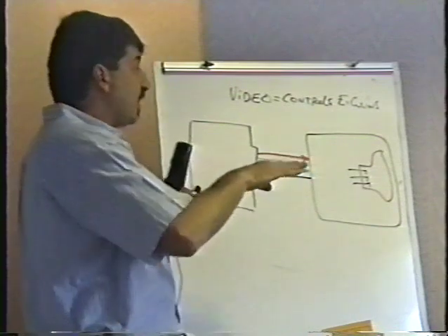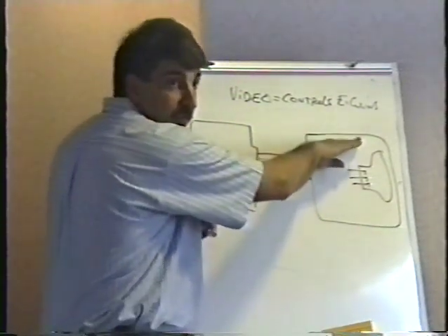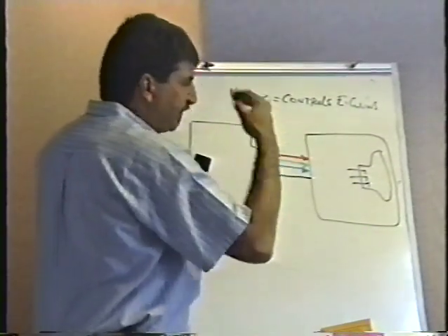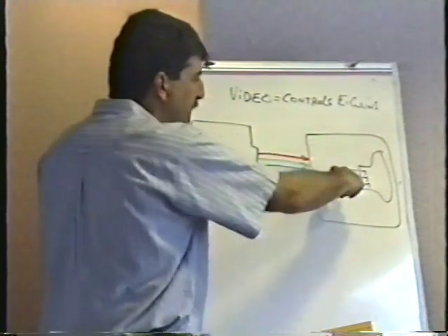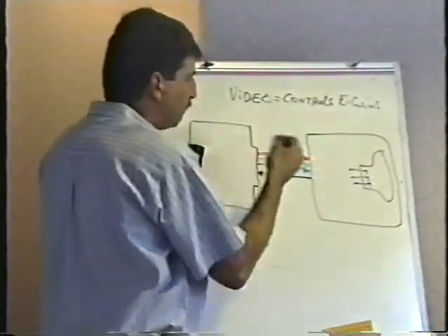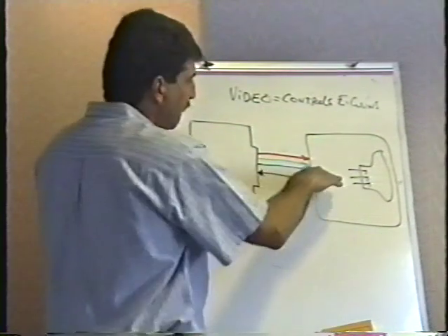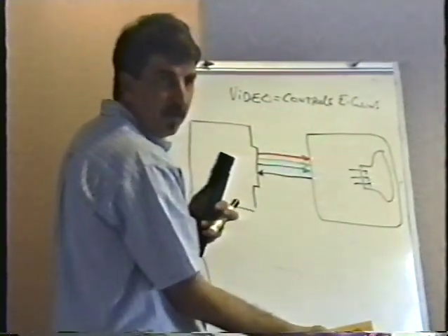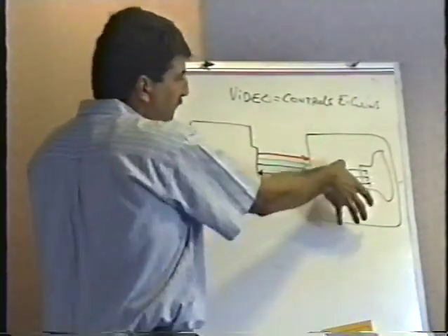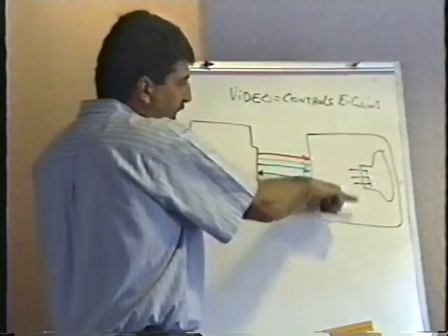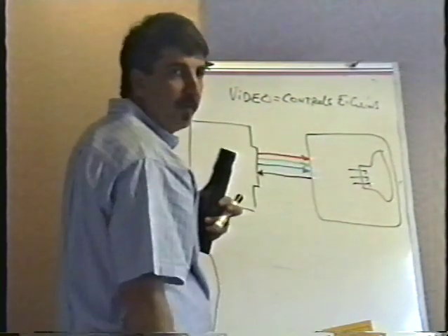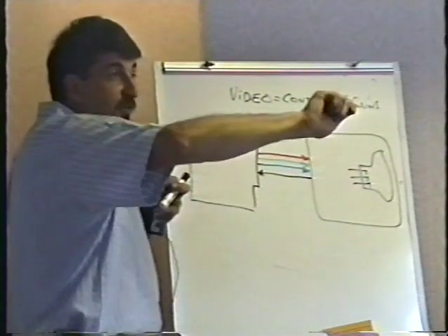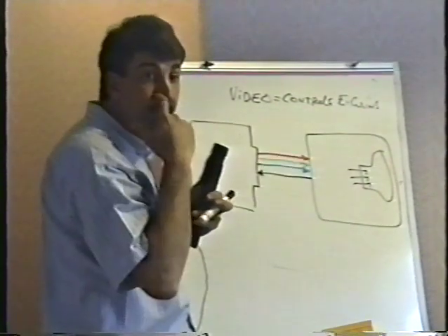For instance, the score displays, we want at the top of the screen, let's say. Well, if the monitor happened to be scanning in the middle of the screen at the time that the computer put out the score display information, the scores would appear in the middle of the screen. And that wouldn't be any good, and the picture would be split in half. The top of the screen would be in the middle, and the bottom of the screen would be on the top. Just as if you had to adjust the vertical hold, let's say, on your TV, and it was halfway up and down.